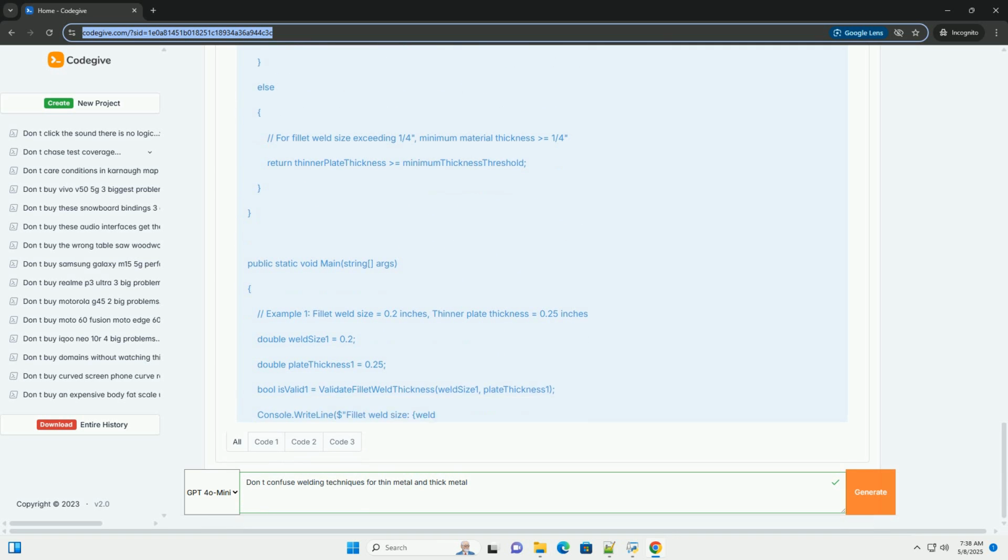Stitch welding: instead of a continuous weld, make short, intermittent welds, stitches. Allow each stitch to cool before making the next, minimizing heat buildup. Skip welding: similar to stitch welding, but the stitches are placed further apart and in a staggered pattern. This helps distribute heat more evenly. Backstepping: start the weld slightly ahead of the desired point and weld backwards towards the starting point. This preheats the joint slightly and can improve penetration. Proper electrode angle: keep the electrode angle low to prevent overheating and burn through. Fast travel speed: a faster travel speed reduces the amount of heat applied to a specific area.